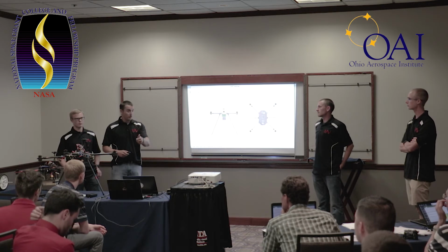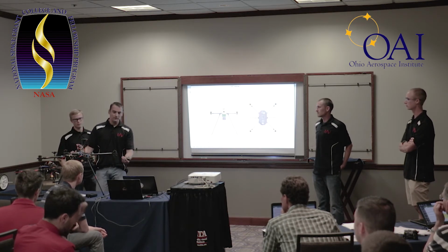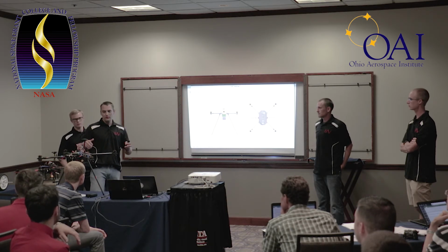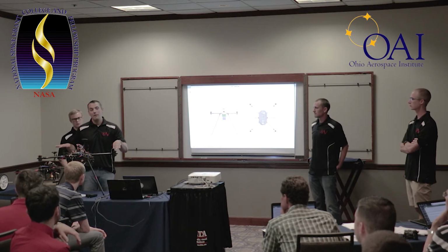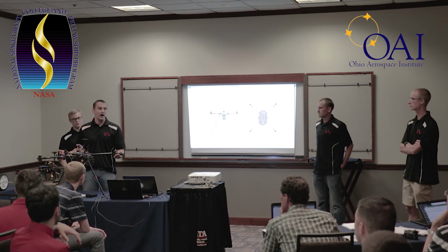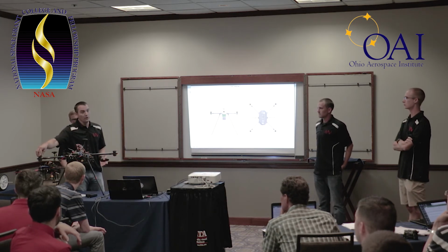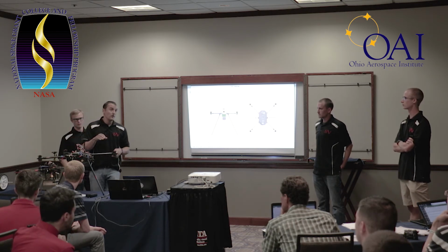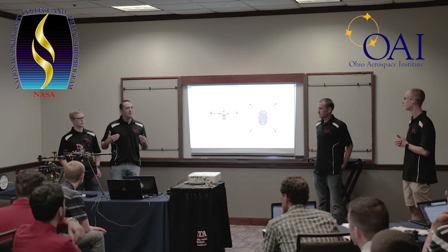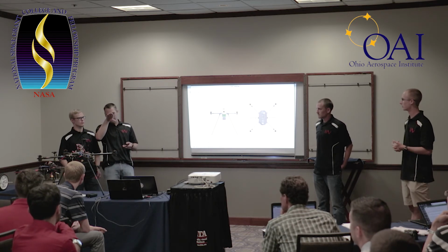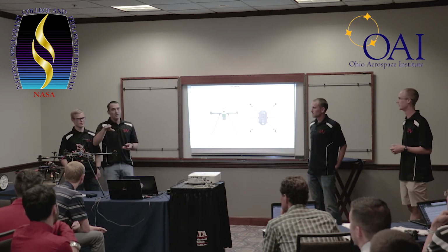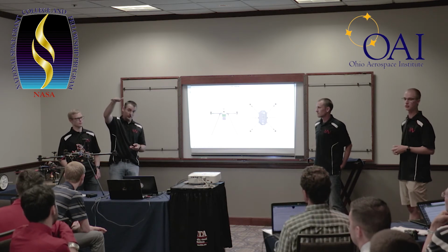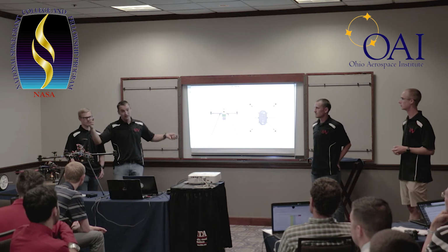We actually had the upper motor, which again, these are 70% less efficient. If you look at the Pixhawk and what the output is, 70% of your throttle comes from the top 4. 30% comes from the bottom. So we lost an upper motor 3 times in flight. And I wish we had more manpower in the lab, and maybe a dedicated video camera operator. But the craft, when I say it didn't move, I mean it didn't. The attitude controller just compensated accordingly elsewhere.